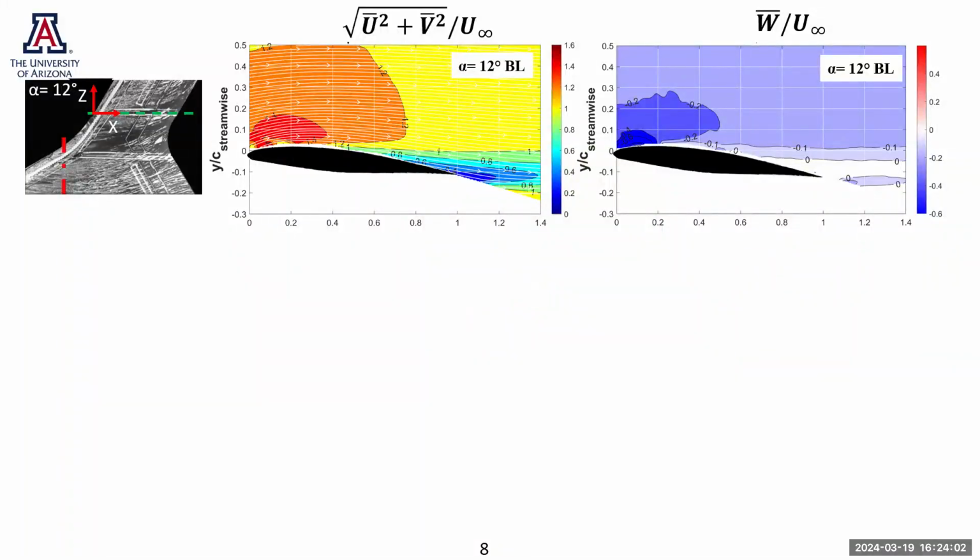We are doing another quantitative experimental technique called particle image velocimetry. We are using a laser which is vertically oriented at this location, just outside of the crank. The process gives us velocity magnitudes and direction that are plotted here. So we have the in-plane velocity magnitude and the streamlines overlaid on top.